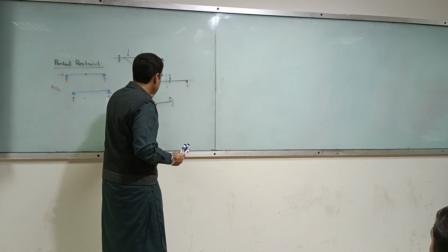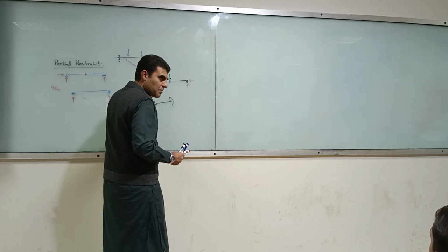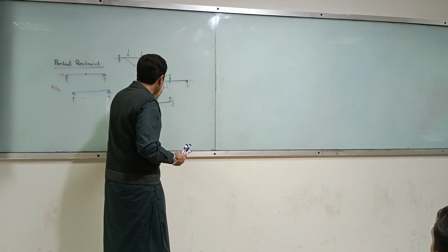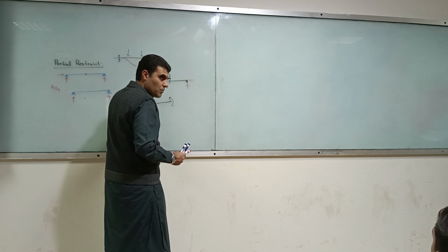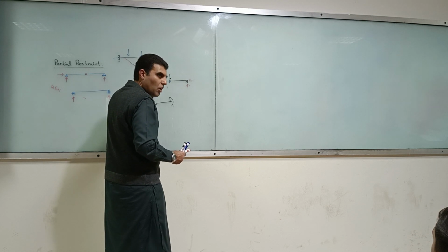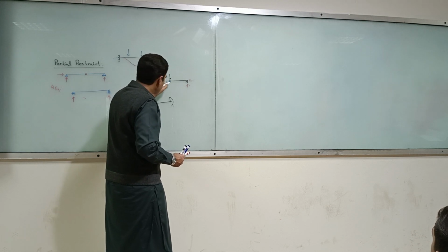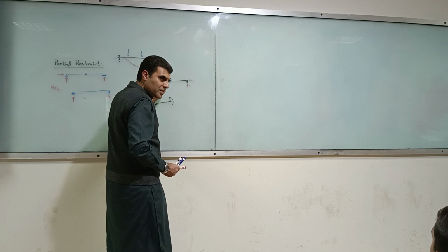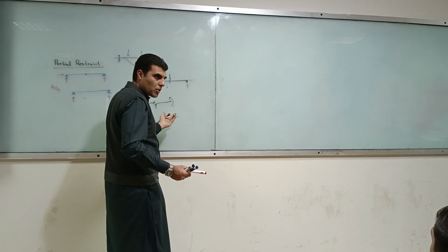So this time, it would be this force times this lever arm. But as you go over there, that moment will start decreasing. Why? Because you will have this one cancelling the effect of that, and the time you reach over here, you will have 0 moment.